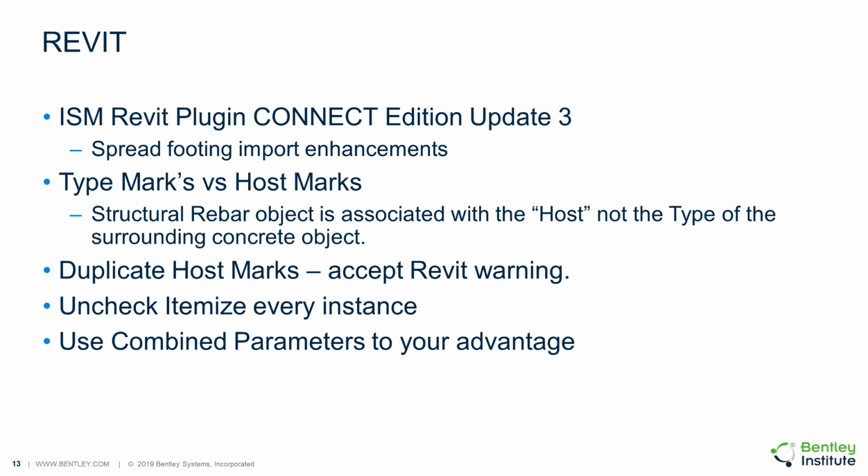Other things to be mindful of are in the schedule properties, you want to uncheck itemize every instance. So you don't want every single instance occupying a row of your foundation schedule. You want that to be grouped some way, and the way to do that is to uncheck itemize every instance. And also use combine parameters to your advantage. So besides just showing the dimensions of our spread footing in individual columns in our tables or schedule, we can combine these parameters into a reinforcement callout or bit of text that's easily understandable. Okay, so let's see that in action.